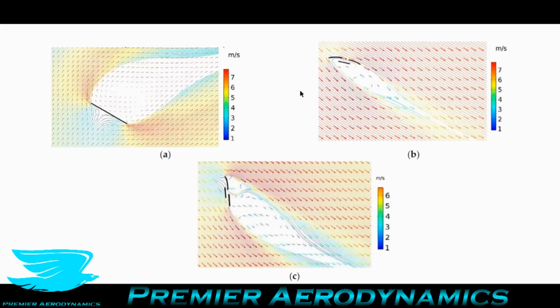And the wake is far smaller. It's probably 20% of the wake compared to the downstroke. So in other words, the wing now is not really disturbing the flow nearly as much as on the downstroke, which is why you don't get as much lift being produced.